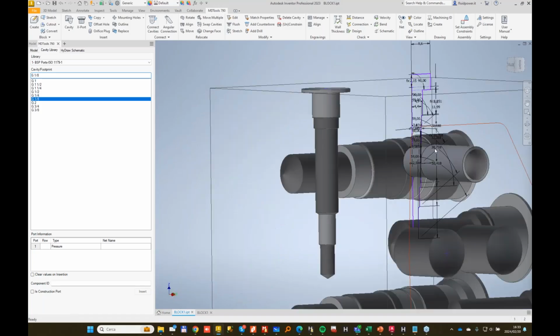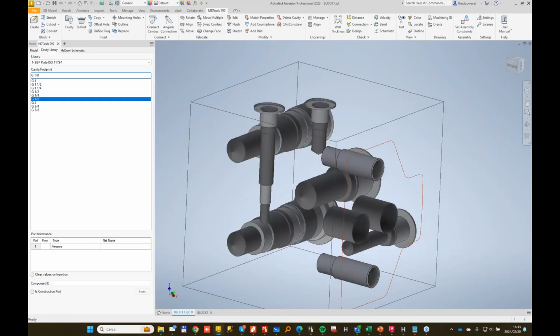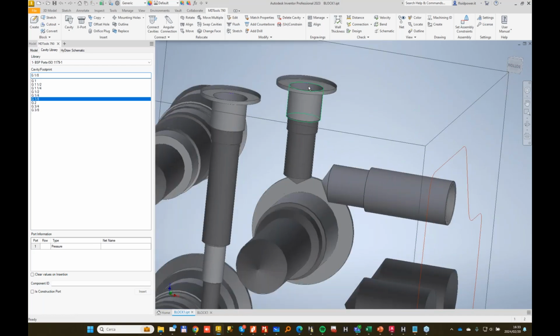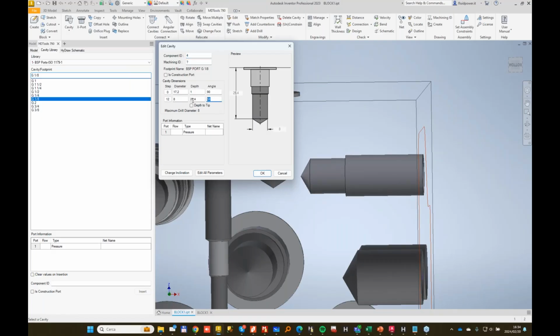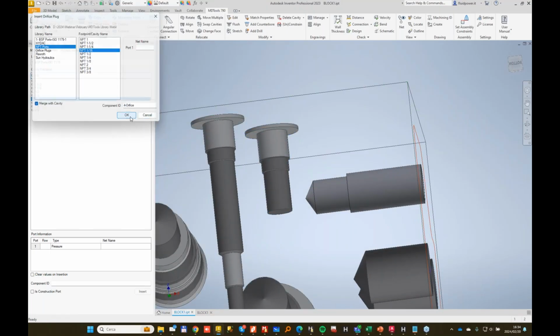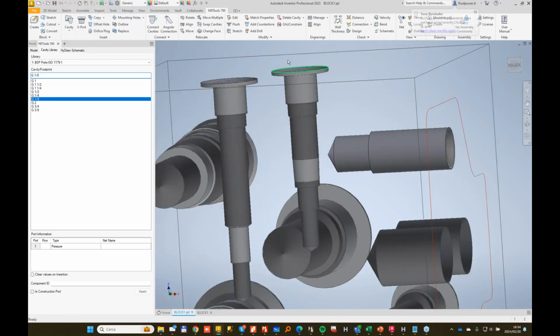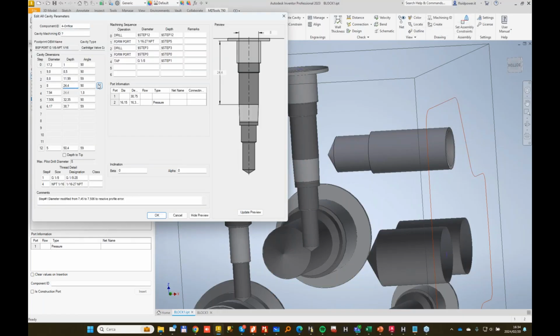It's not always happening, but it means that there is some problem with the sketch definition of this block. As a workaround, and this is also solving another problem for the precision, if you want to add an NPT, NPTF 1/16 in a cavity, first change the angle to 90 and then add the orifice plug. That's just a workaround, it will work. And the other advantage of this is that you will really be able to control the depth of that NPT port more efficiently, because then it's really a precise position, and we can make it 30.